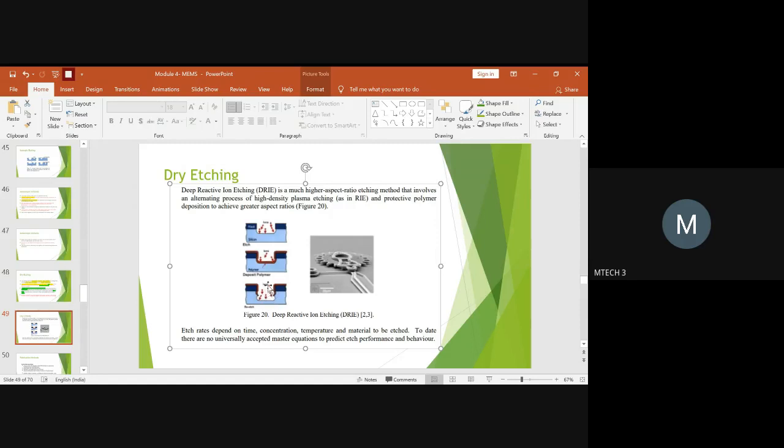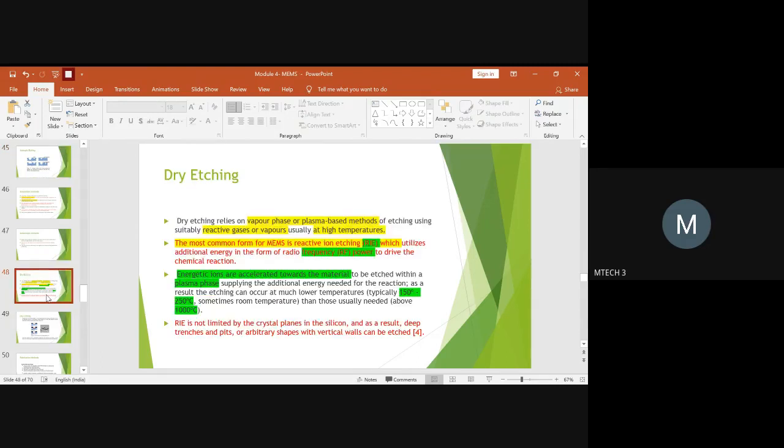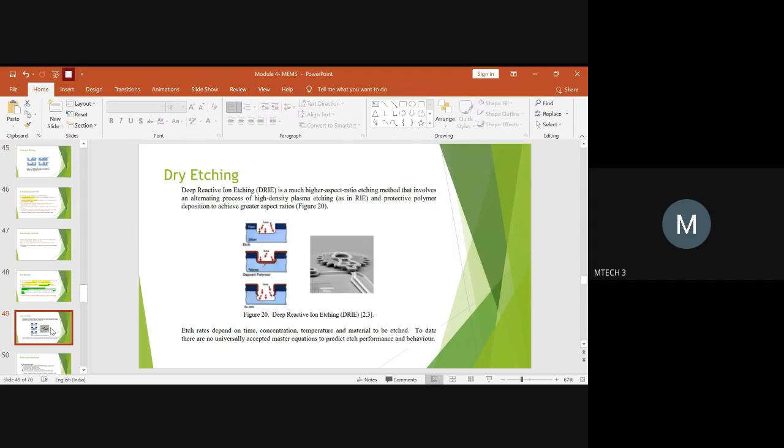So you have etched so much material here. When you observe the previous case of normal etching, you are not removing that much material. But when you go for deep etching, you can see that this is normal etching, and to go for deep etching you usually apply a protective layer so that the other boundaries will not be affected, and then you again re-etch. So about 3/4 of the given material has been etched out at a particular area to get the required pattern. This is achieved by means of deep reactive ion etching. So you should be able to understand this also.